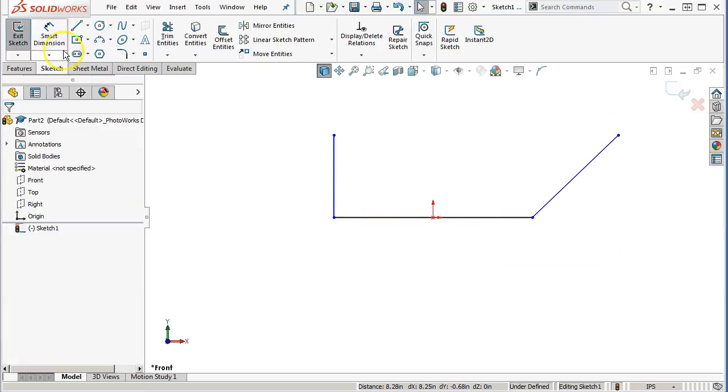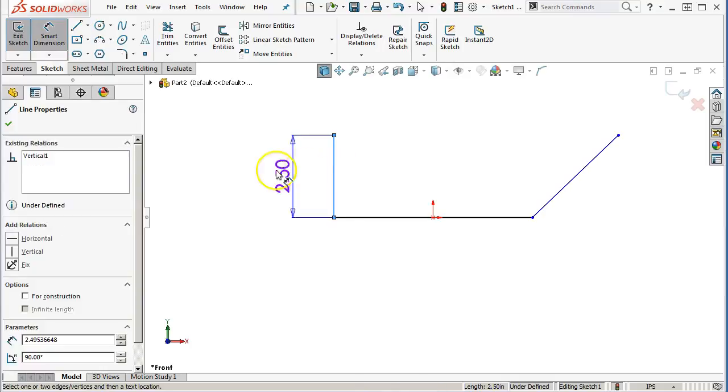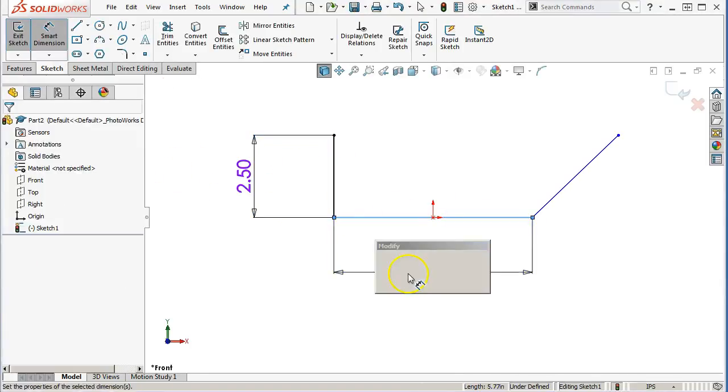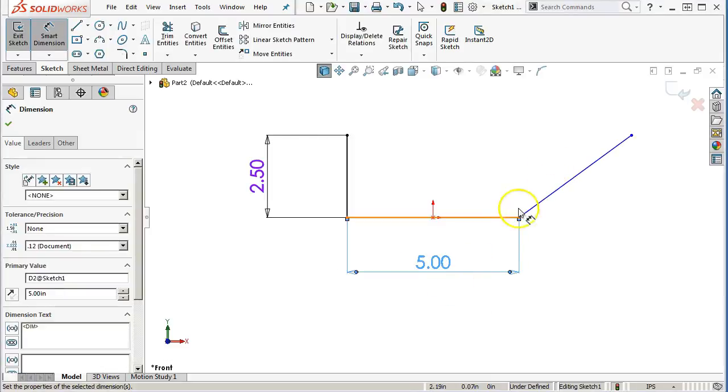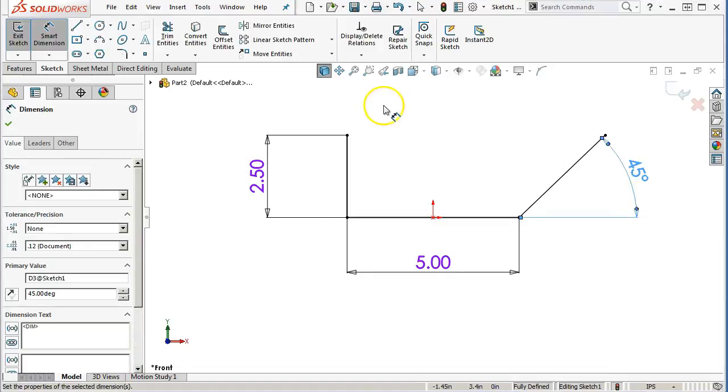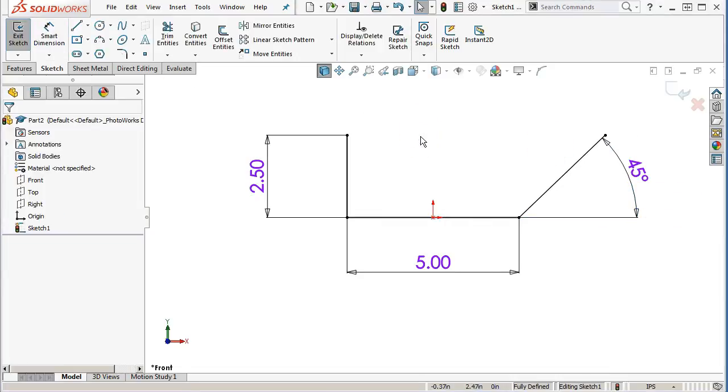Nope, didn't quite want that dimension. So 2.5 is okay, 4 on the base, 5 on the base, 45 degrees, and whatever the length comes out. All right, so that profile will generate valid geometry, but it's also going to give me my 2 initial bends. All right, so we were 4 by 2. Let's stay with the by 2 sort of.